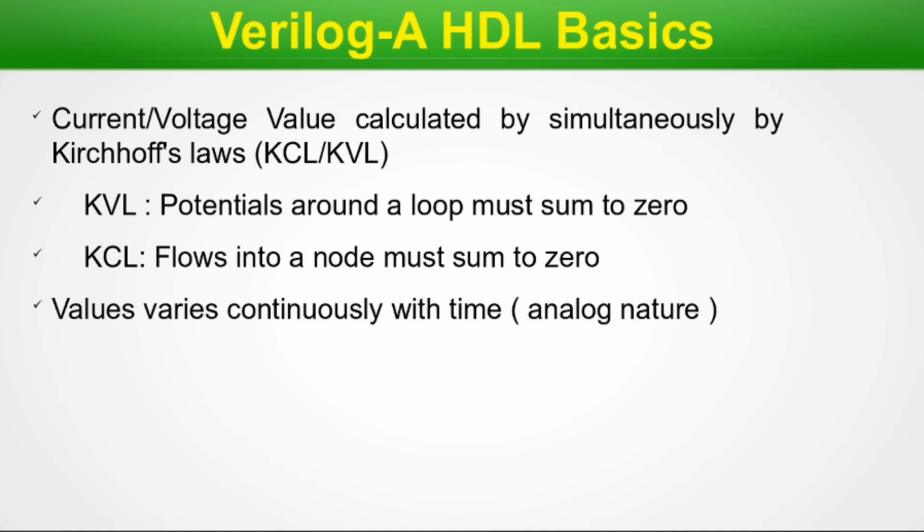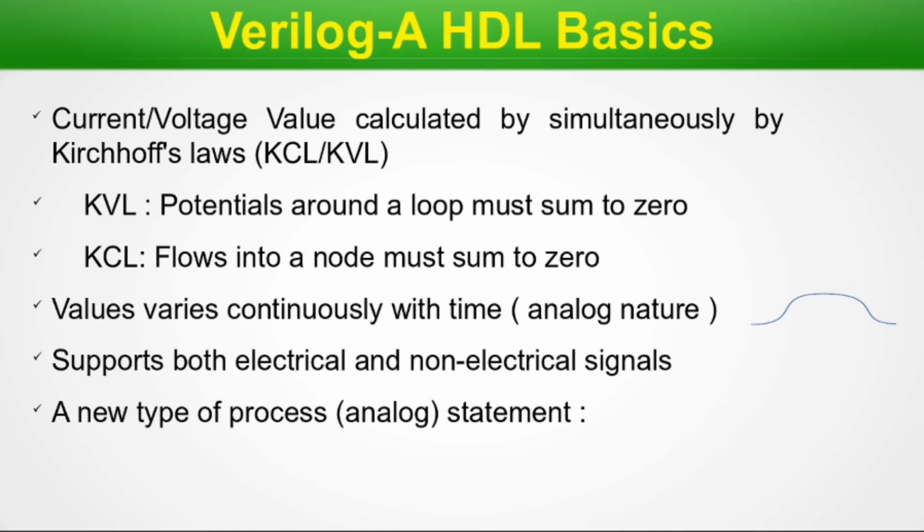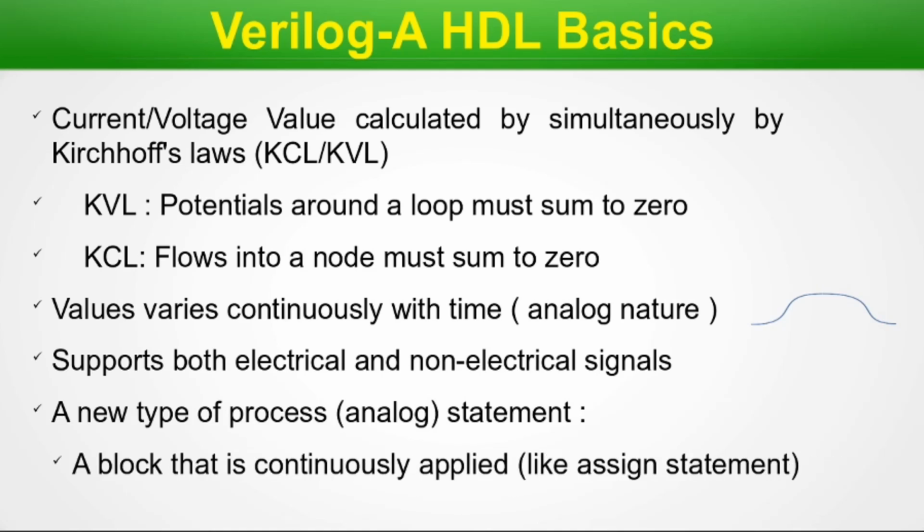Values vary continuously with time. They are analog in nature. So when we see a waveform like this, we know that with time, it varies continuously. In this waveform, the Y value is different at different time points, where time is independent on the x-axis. Supports both electrical and non-electrical signals. A new type of process, the analog statement, is introduced here. This is a block that is continuously applied. It's like an assign statement, similar to the assign statement we used in Verilog. Later we will see this analog block and we'll understand how it is continuous.